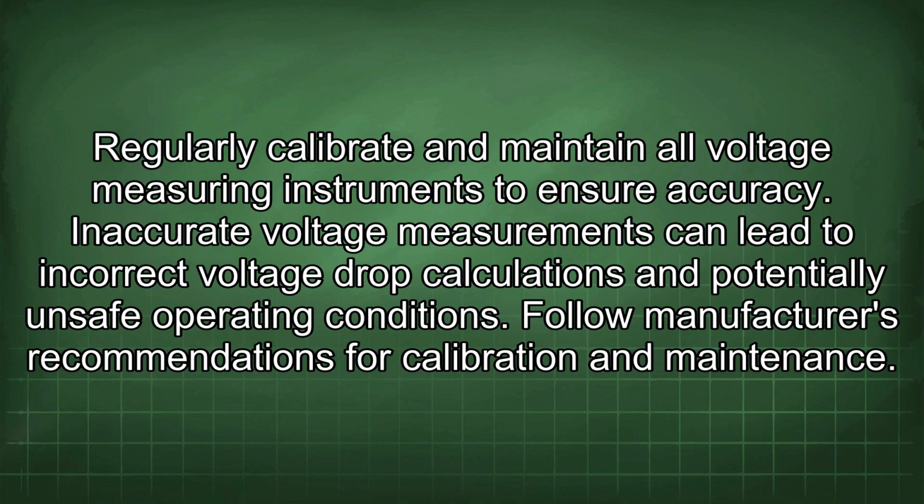Regularly calibrate and maintain all voltage measuring instruments to ensure accuracy. Inaccurate voltage measurements can lead to incorrect voltage drop calculations and potentially unsafe operating conditions. Follow manufacturers' recommendations for calibration and maintenance.